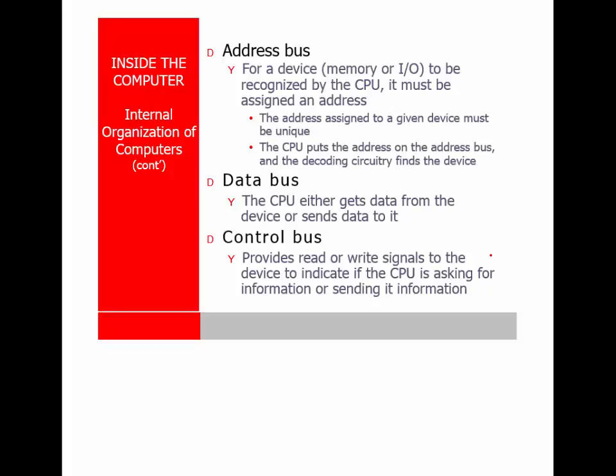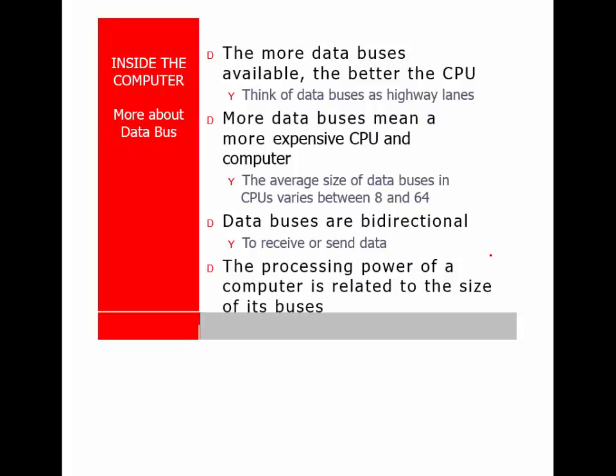The data bus is the information we send back and forth. And the control bus is basically the microprocessor controlling. He's playing the traffic cop directing traffic. This data is going out. This data is going to an I/O port. This data is going to memory. This data is a write, so it's going out from the microprocessor. There's a read operation, where you send me the data. It's telling me various controls. So I warn you right now, on the final exam, I'm going to be going through the various I/O pins on the 8086, and I will be asking you what the various control lines do. As I cover those, we'll point those out.